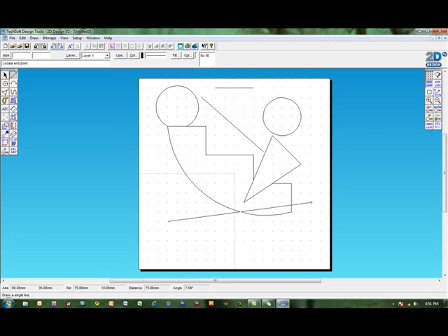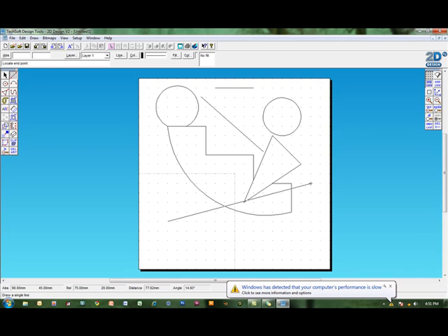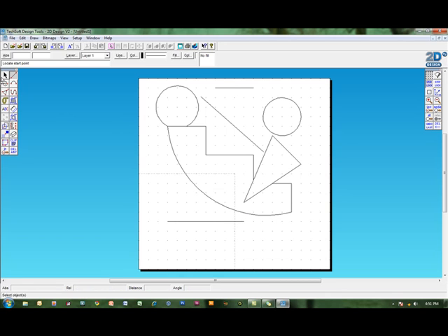I raise it up a centimeter, it tells me that, or a centimeter and a half. It's now 7.5 centimeters across and 2 centimeters up. So that's just helpful if you want to work out exactly how long a line is. Now once you've made your line, so for instance here, if I've made this line, I can see it's 4 centimeters, but if I forget, we can't just select on it, and I don't think it tells you how long our line actually is because all those values down the bottom are changing. So what we do is we get our Smart Dimension tool, which is up here.